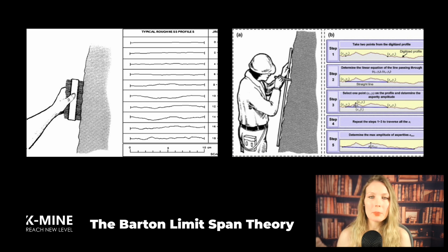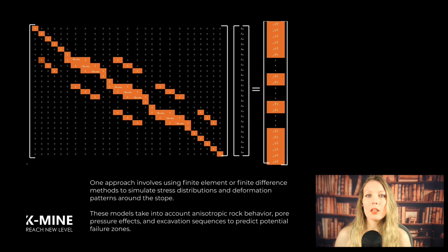risk of collapse. A key insight from this method is the weaker rock masses require narrower stopes and additional support structures to prevent failure. The Barton approach is often used in conjunction with the Matthews stability graphs to refine stope design criteria. For deposits with highly variable geological conditions, numerical modeling techniques provide a more precise means of stope optimization.